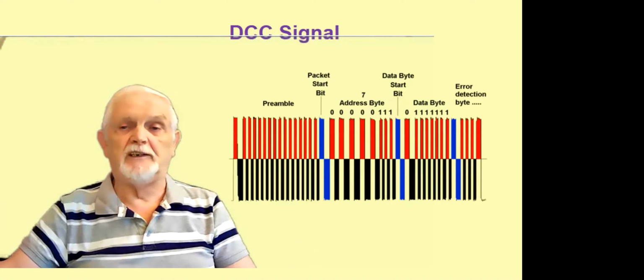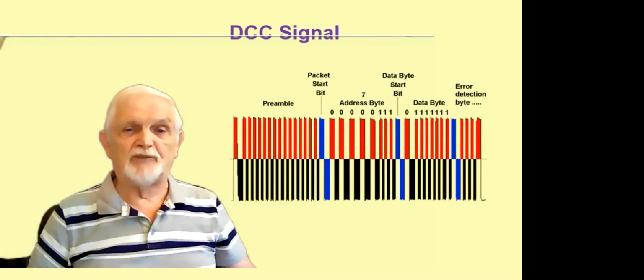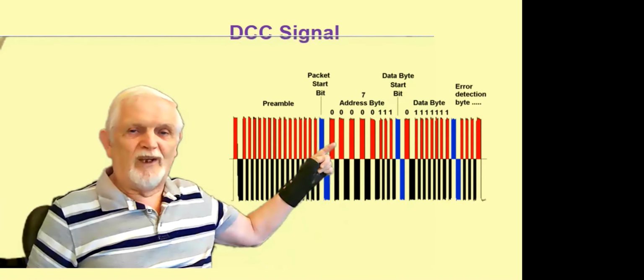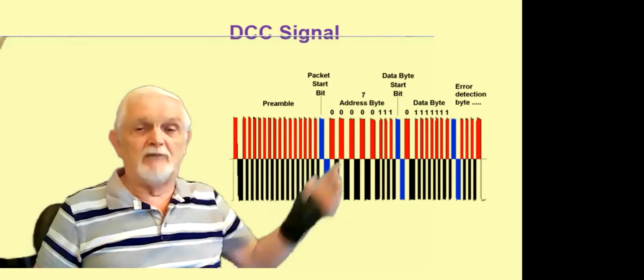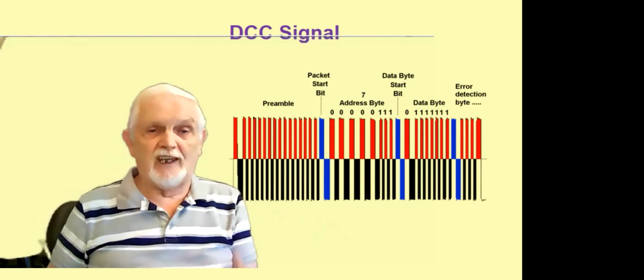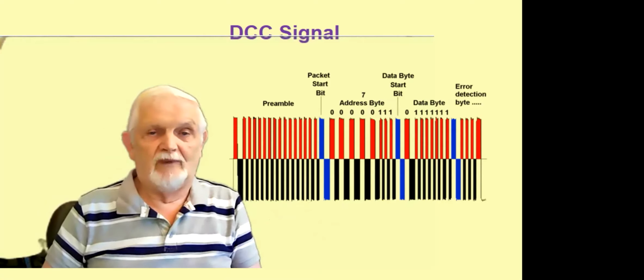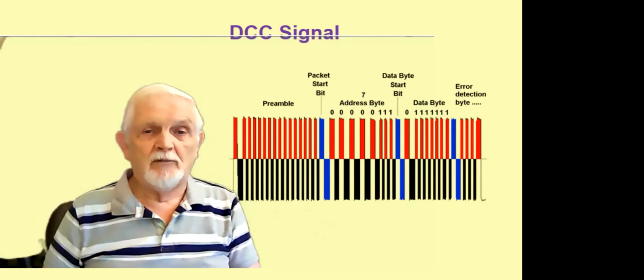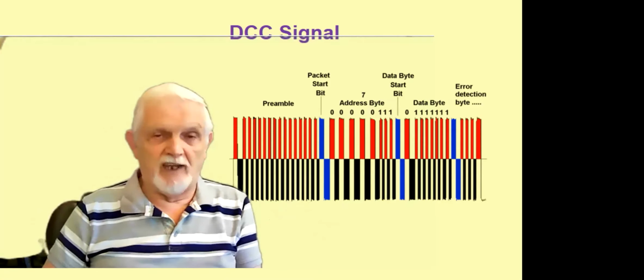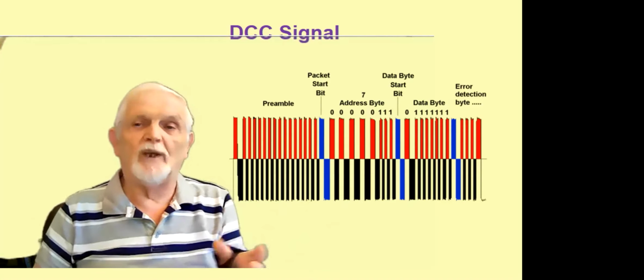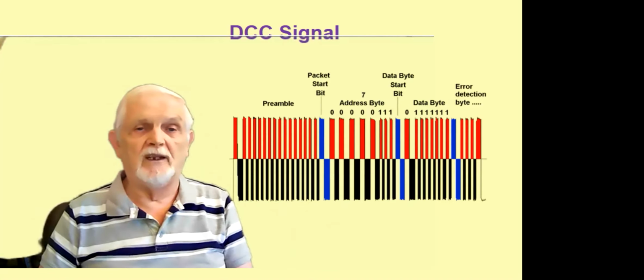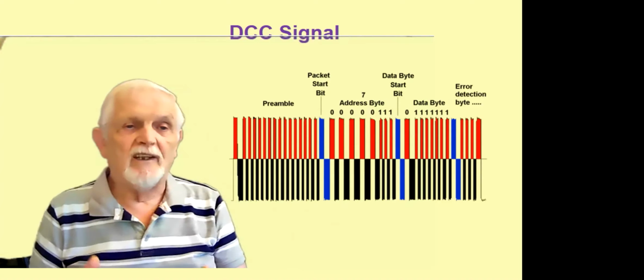There's DCC. Can anybody spot wide pulses and narrow pulses and gaps in between? We're using the exact same principle, obviously updated, but the data we're sending is very similar, just a bunch of narrow and wide pulses and gaps in between to pass over the information.